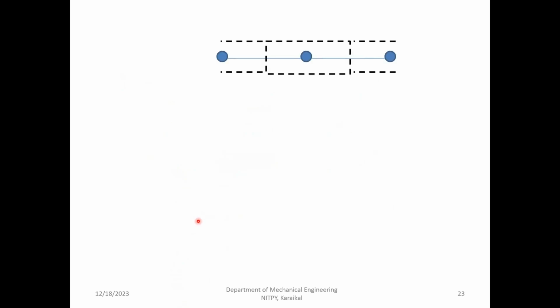So this will be the turbulence modeling. We can look in Fluent. There will be options of various turbulence models. So you must choose your model correctly. Some models are specifically for flow across cylinders. Some models are for flow inside pipes. So you must choose those correctly.